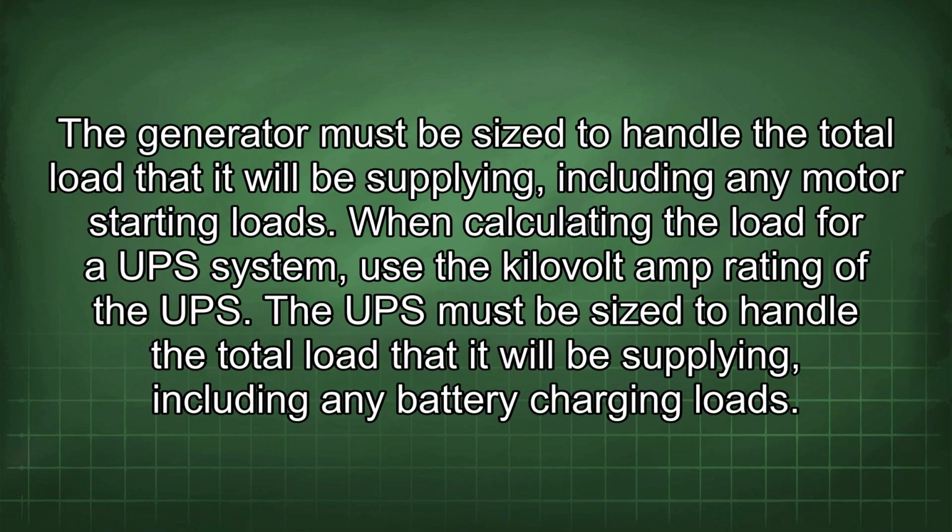The generator must be sized to handle the total load that it will be supplying, including any motor starting loads. When calculating the load for a UPS system, use the kilovolt-amp rating of the UPS. The UPS must be sized to handle the total load that it will be supplying, including any battery charging loads.